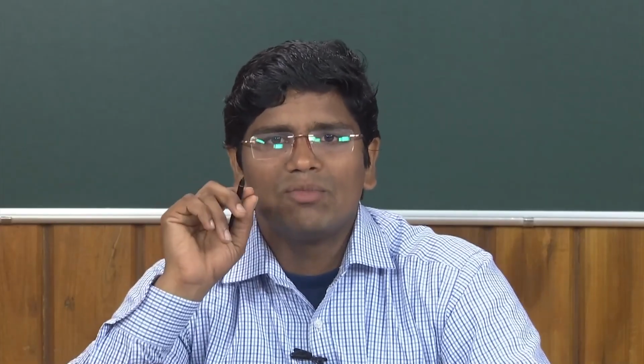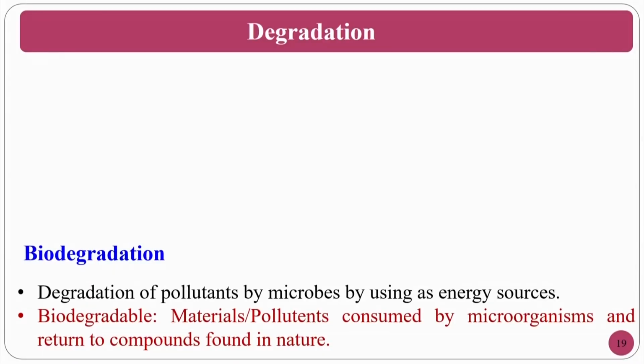Degradation, as I said: before you dump this cutting fluid, you have to degrade it to a good level. That good level is one where it should not cause any problem to the water bodies or the humans. Okay. So, we are talking about biodegradation, because why biodegradation? You are dumping into the water body, and the water body contains a lot of living organisms. So, if it can be degraded by those microorganisms, that is well and good, so that the humans who are there or who depend on it will be safe.